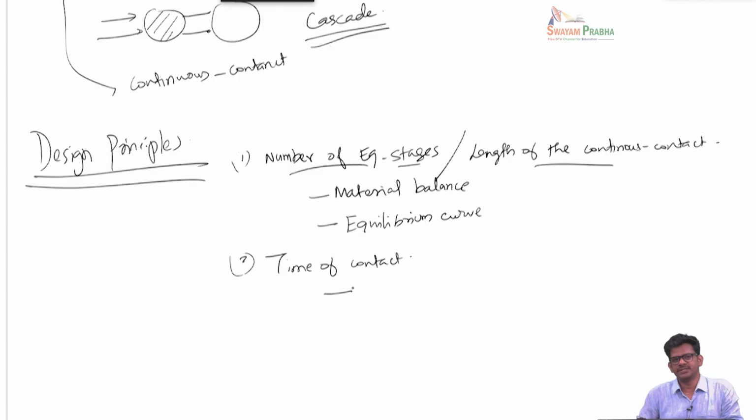In terms of stage-wise operations, what we are basically asking is, what is the stage efficiency. We have not defined stage efficiency yet, but roughly it relates to whether a stage allows a complete equilibrium composition or falls short of equilibrium composition, to what extent we have achieved the mass transfer.